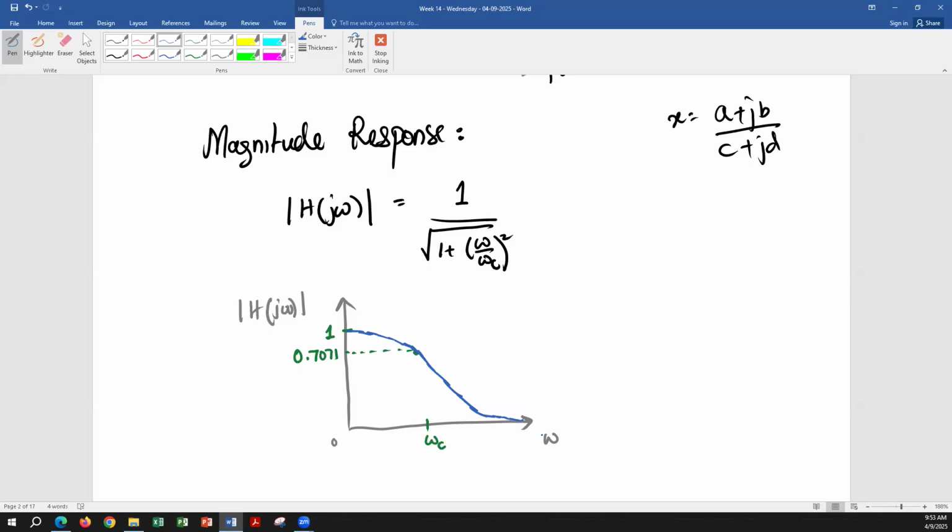If you don't do that, and if you're plotting the response of a low pass filter, you have the value of capacitor, you have the value of resistor, and you found the magnitude response, and you're plotting it. Let's say your cutoff frequency is 1000 hertz, 1200 hertz, and you're plotting it up to 20,000 hertz, right? That means everything is pretty much happening in the earlier part of the frequency range, and nothing is happening in the later part.